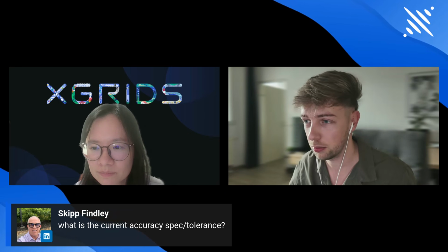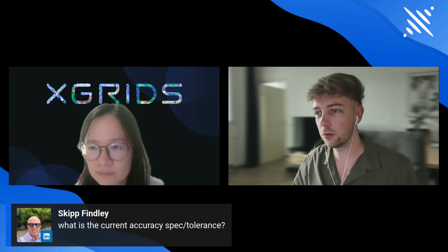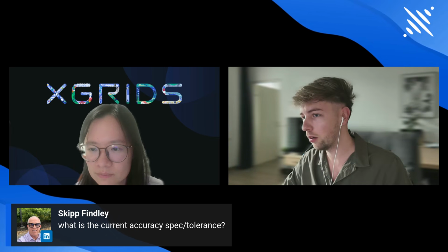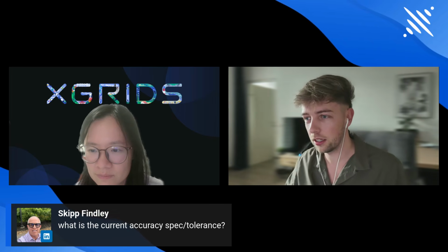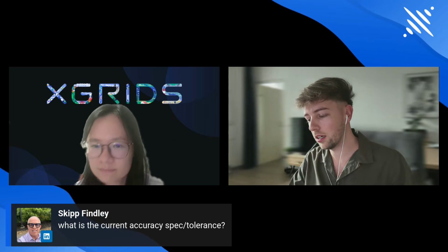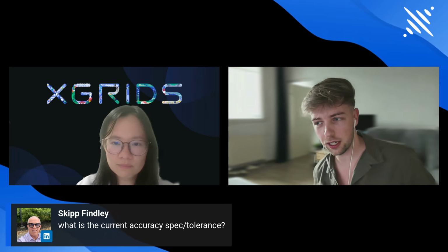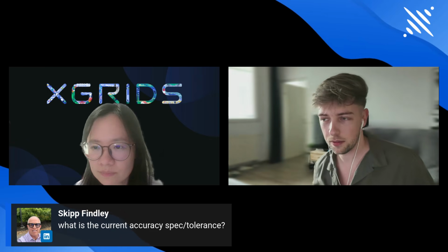At max, it can be perfectly accurate as well. This always depends on reflection, on how many georeference points you use, how many angles you use for scanning, what your starting point is, and whether you work with an RTK. But in general, you can say 1 to 2 centimeters. There you get the difference.